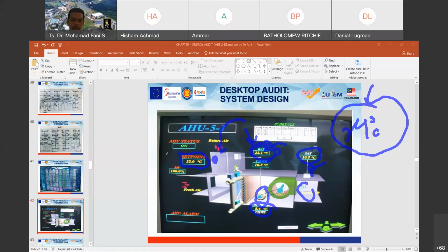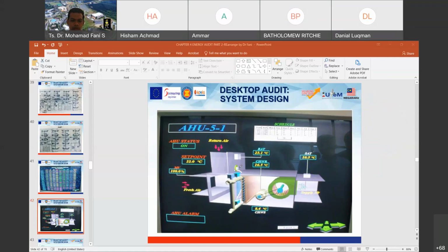On how they will maintain 22 or 23 near the set point: it is to regulate the actuator valve here. If the valve is open 100%, it will run the motor at 100% operation, and also draw the chill water flow to the maximum, the flow rate to the maximum.